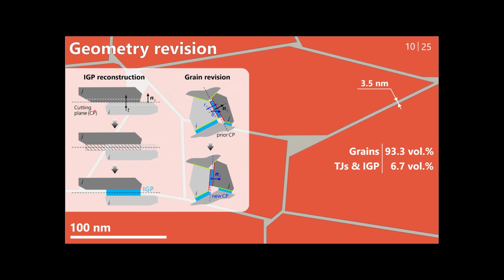What does it mean? It means that if we have a certain geometry, it will not necessarily be efficiently meshed. For a high quality meshed model, we should regularize it and get rid of small elements which are less than the mesh size we are going to use.